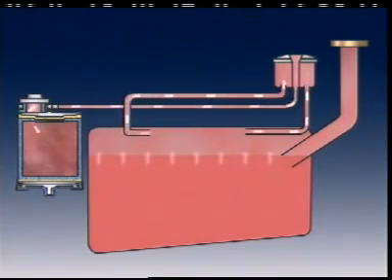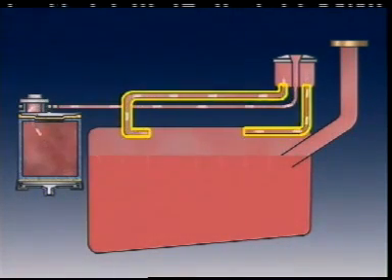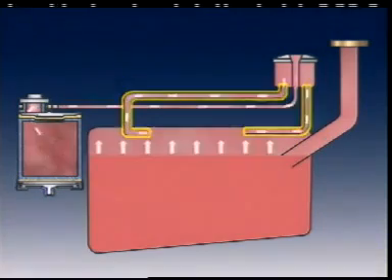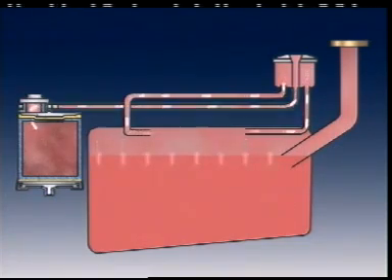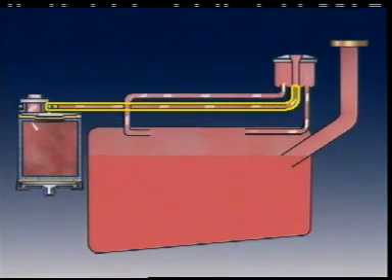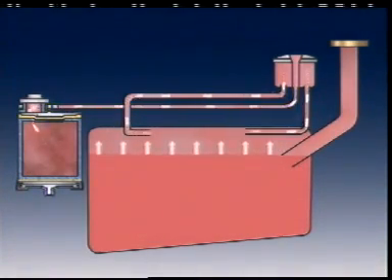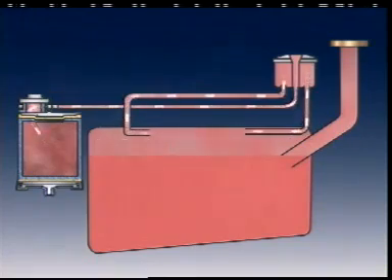A liquid vapor separator may be connected to the tank by a number of tubes. This separator allows liquid fuel to separate from the vapors and return to the tank. A vapor line is connected to the vapor space in the tank, or the liquid vapor separator. It carries fuel vapors from the tank to a storage volume.